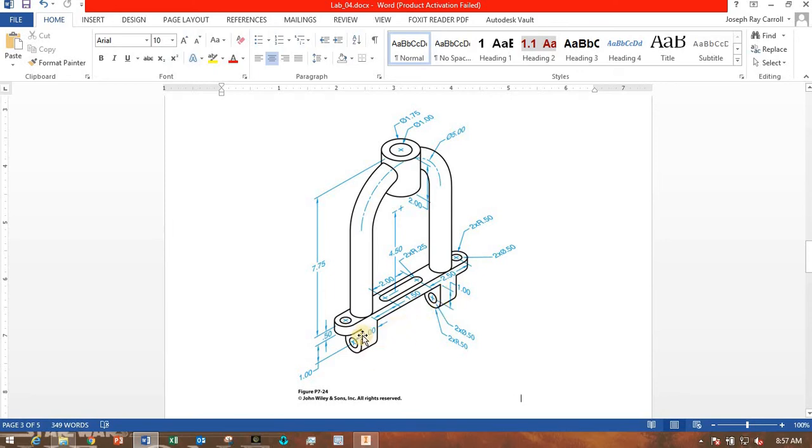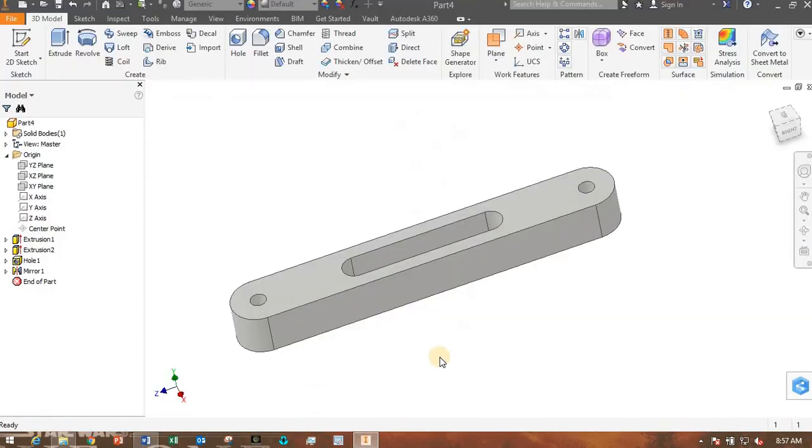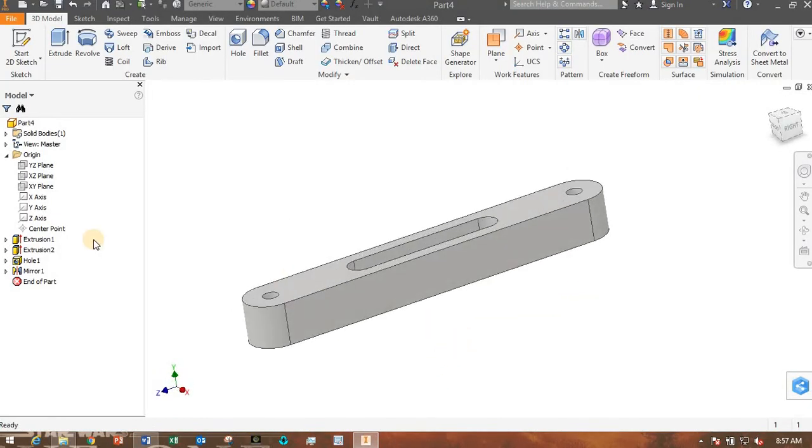Okay, well, I want to basically make the same type of process. I would want to sketch this profile here and extrude it in this direction. But what plane could I sketch on? Let's look at that. Not that plane. Not that one. Okay, how about this plane? The problem is that plane is right there in the very middle, and I would want it to be further to the left, or yeah, further offset.